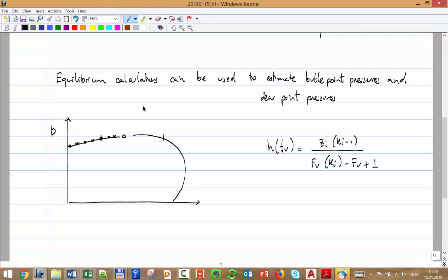Okay. So what happens if we are on this bubble point line? What can I say about FV? What is FV? Number of moles of vapor divided by total number of moles, right? Exactly at this line, what do I have? Just the first very small bubble of vapor, right? Everything is liquid in this area. And when I'm exactly crossing that line, I have the first incipient bubble coming out of the liquid. Therefore, on all of this line, FV is simply equal to 0, no vapor. And on the dew point line, FV should be 1. So that really helps my calculation.